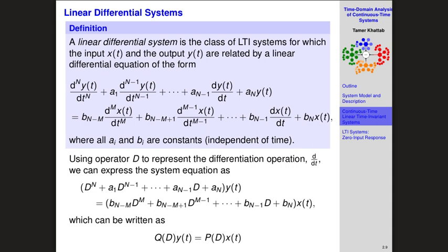Yes. The problem with derivatives is when you deal with things that have abrupt change, like a unit step, so something starts at a certain point, or when you deal with high frequency components, because the derivative of high frequency components gives you something with very high frequency. What's going to be the derivative, higher or lower? Whenever you have a higher frequency change, like an abrupt change, you get a larger value of the derivative, which means that even though your input might be bounded, because it has some abrupt change or changes very quickly, the output might blow up, right?